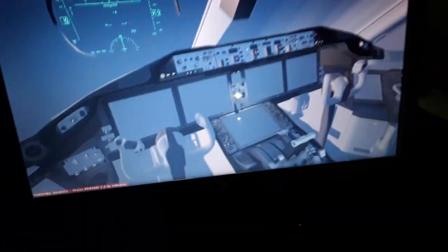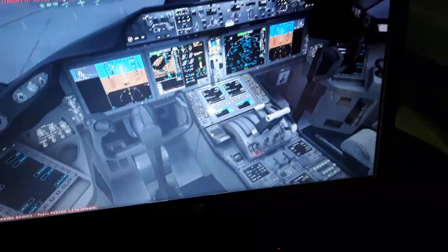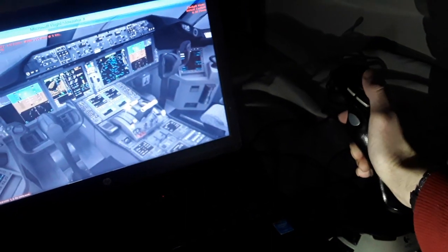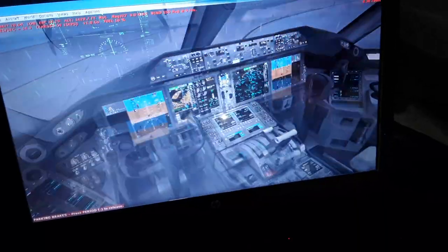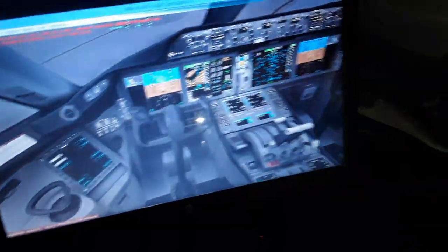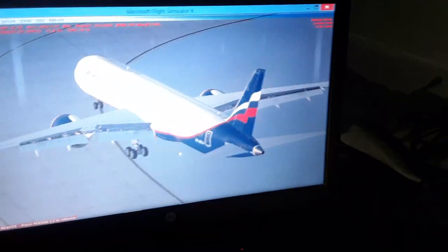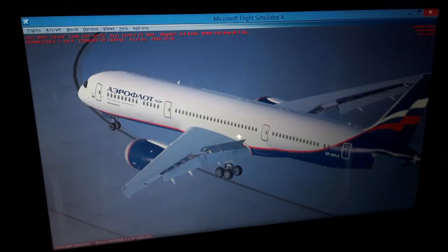The rudder control. We use the rudder pedals over here, as you can see, for the rudder control, only rudder pedals, left and right. So we control the rudder pedals like this. Also we have the control of the tiller, the nozzle steering. In many aircraft you have them interconnected. So from 0 knots you also control alongside with the rudder.